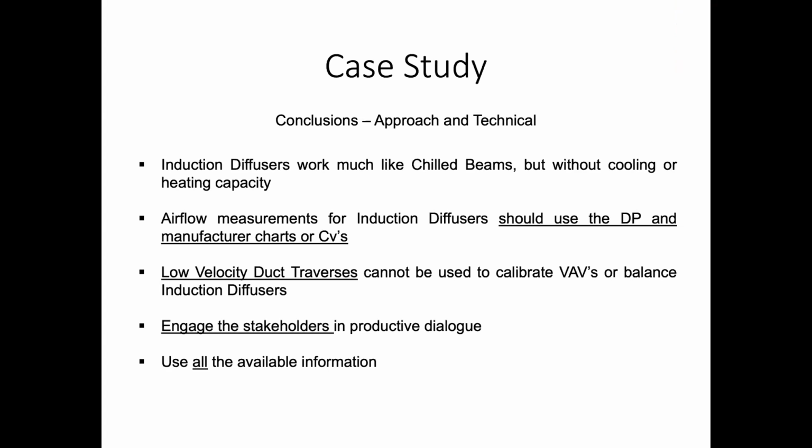And I have two in here that have some numbers in them, if you don't mind popping up the Q&A button so you can read along. This one's from Michael. Evergreen promotes a plus or minus 2% reading of 0.001 in WC, from 0.01 in to 10 inches WC. If you were to use this meter and come up with the same results, do you believe it could still be attributed to meter or measurement inaccuracy, or would further investigation be required?